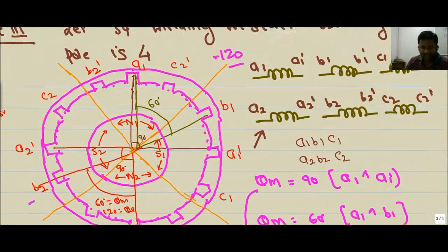So we have understood that the stator has a three-phase winding which is able to make a four-pole machine in the stator. Alternatively, a four-pole rotor will be there. The electrical angle is different from the mechanical angle, and in the expressions we consider the electrical angle.